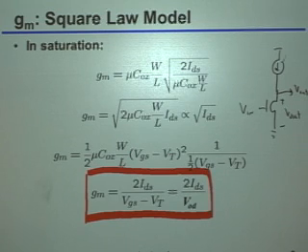And of course, as I hope you all know as well, there's a similar VDSAT that would be in that physical current source. So again, if you decrease that VDSAT on both sides, the actual swing you could get at the output would go up. Okay? Does this make sense to everybody? So by the way, that would tend to imply that you'd like to have a small VDSAT, or equivalently a small VOD.